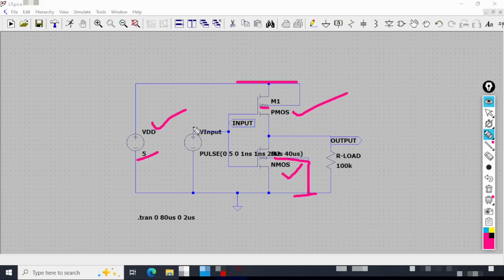Next, we have another input which will be used in the input of the CMOS inverter, and here we'll check the output across the load resistance, which has a value of 100 kilo ohms. Here we are using a pulse command to create an almost square wave, although we have rise and fall values here. So in actual practice it will be a little bit slanting when it is rising. Now I think all of our circuit components are done. We do have the ground, so everything is placed, and we will be doing a transient analysis. And this biasing voltage is a DC voltage.